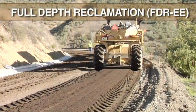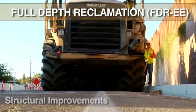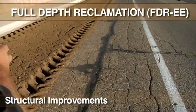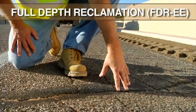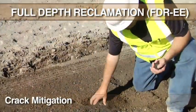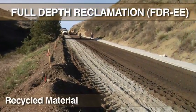The FDR process with engineered emulsion has many advantages over a typical remove and replace operation. FDR-EE can provide necessary structural improvements to the failed roadbed. This is accomplished by stabilizing the existing in-place material and upgrading their structural value. All forms of cracking are mitigated, since the entire cracking pattern is pulverized and disrupted. The granular material is then stabilized with an engineered emulsion. The recycling process provides a low environmental footprint.